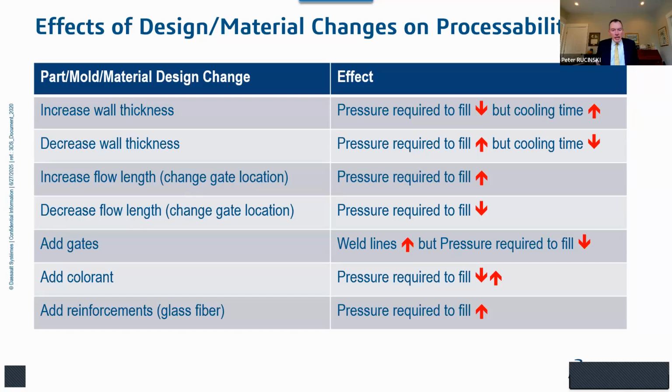And I've certainly seen many cases in the past where we add a colorant to a plastic material where it actually increases the viscosity of the material. It increases the resistance to flow, requires higher pressures and maybe even temperatures at the injection molding machine.